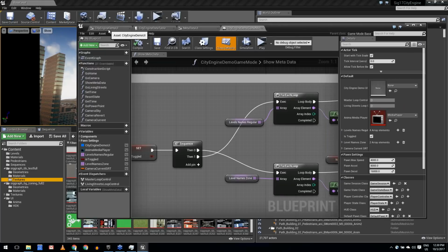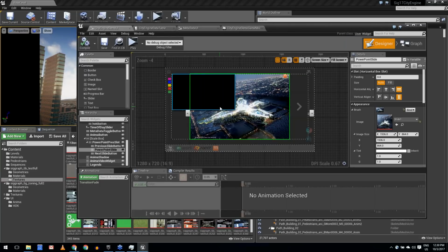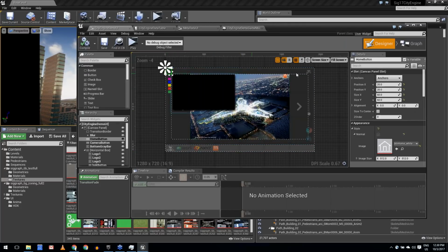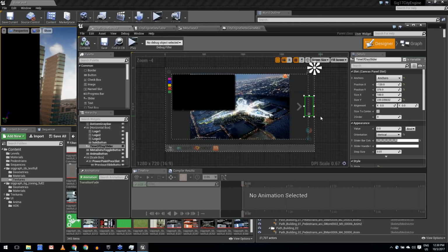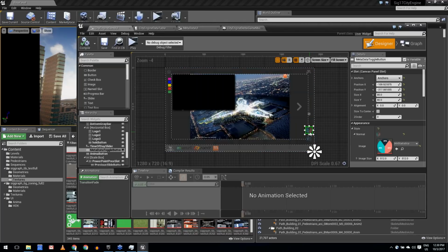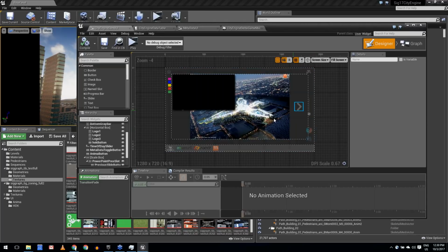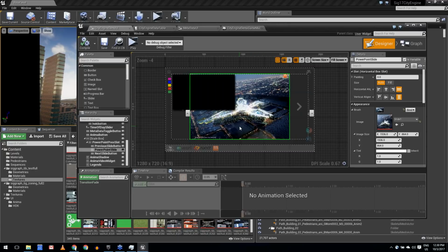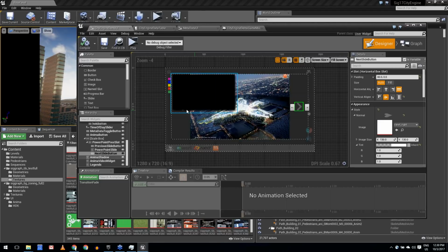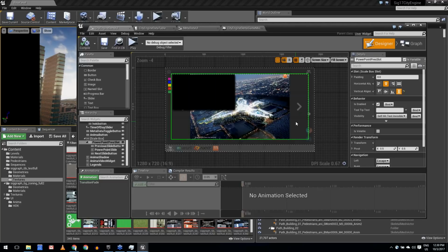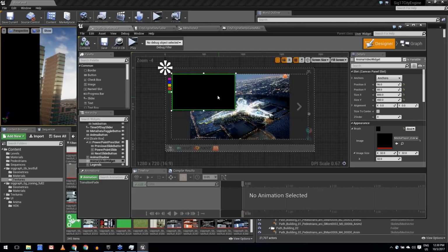So for example, I made reference to the PowerPoint-like presentation. Well, Unreal allows for creating 2D UIs where you can create buttons, and those buttons are basic images that you load in, and then you assign them some logic and you tell them what to do. So in this case, we've loaded the images that we extracted from PowerPoint, and we created right and left arrows, and then we assigned logic to say, when this is on, show the image, and then play back the video in the background and blur the background, and so on. For example, this black square here is a placeholder for the video that you saw when people were walking in.